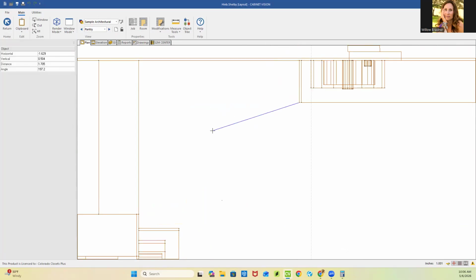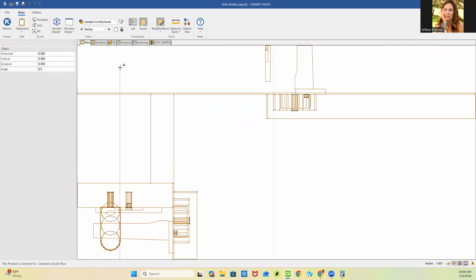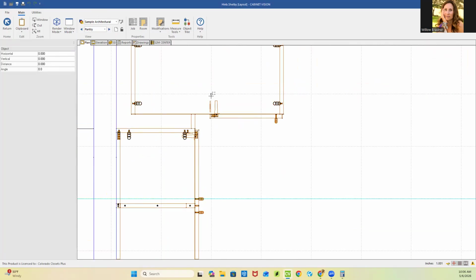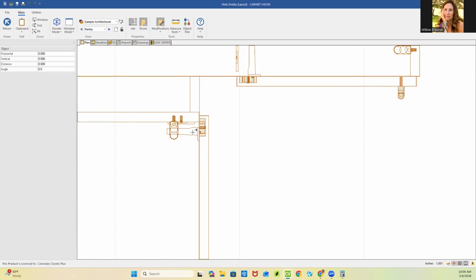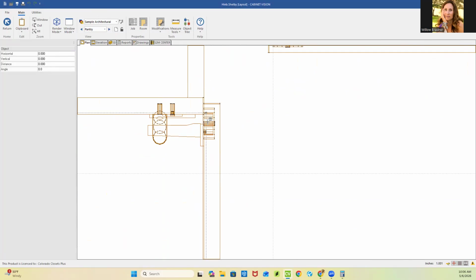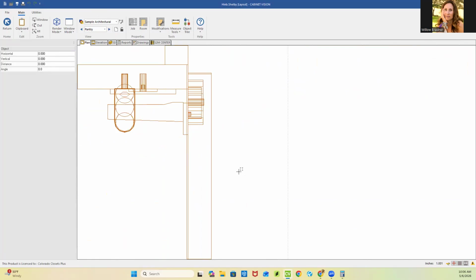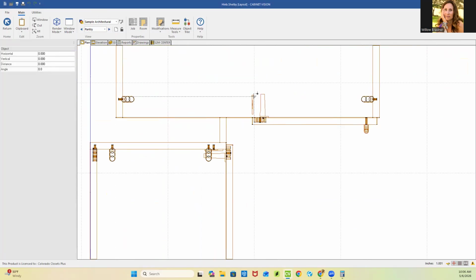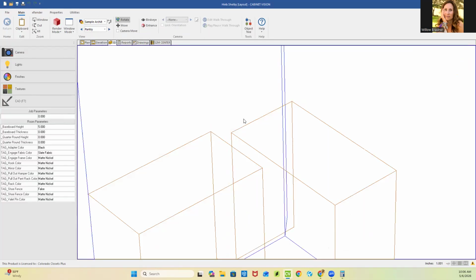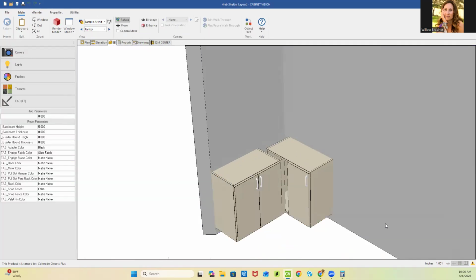Great. So now that our door is where we want it, all we have to do is fill in behind it. Most importantly, this hinge plate, we want it to look like this, because the hinge has a little bit of adjustability, but it doesn't have that much. If the hinge plate is positioned way out here, when they actually put the slab on, it's not going to fit because it's going to suck the whole door to the left. So we want to fix that, and I'll show you how to do that. But right now, as we're going through our steps, things are beginning to look pretty good, right?